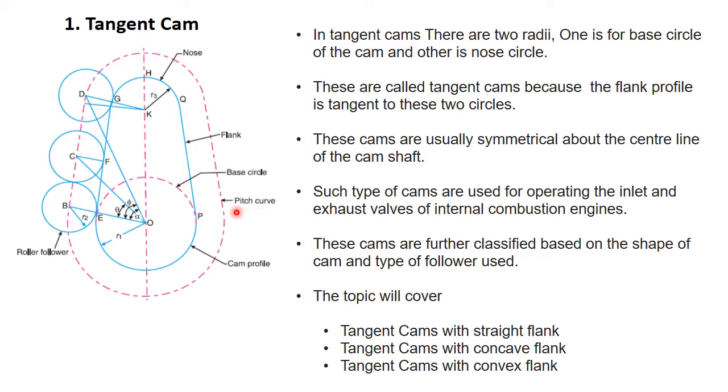Then this total is called the cam profile. Such types of cams are used for operating the inlet and exhaust valves of internal combustion engines, and these cams are usually symmetrical about the center line of the camshaft. We can see this is symmetrical about the axis and center line.